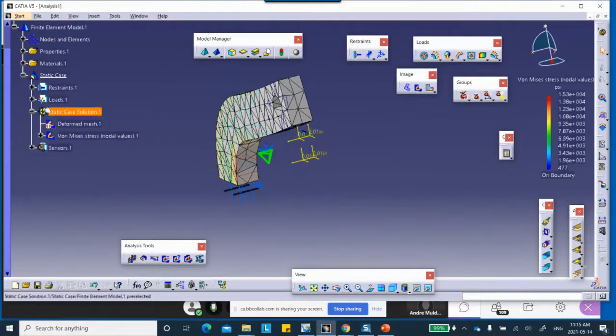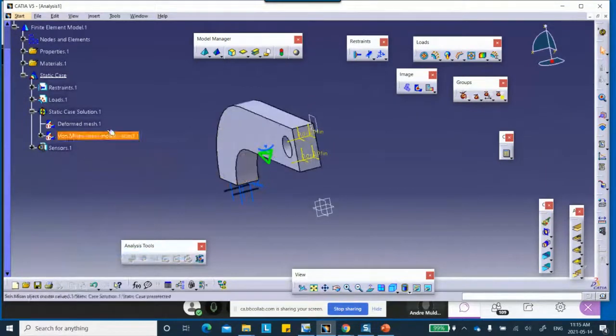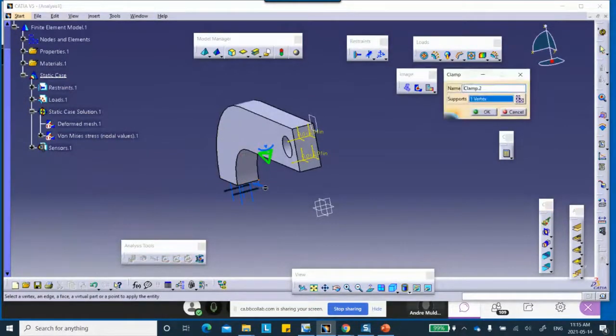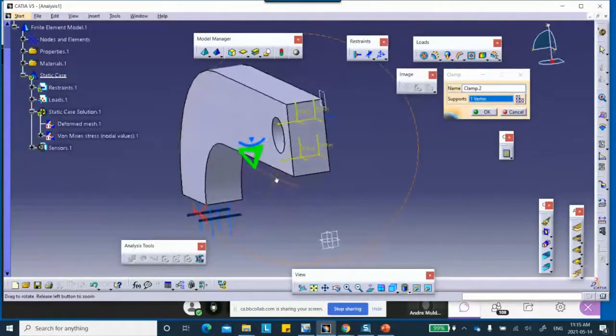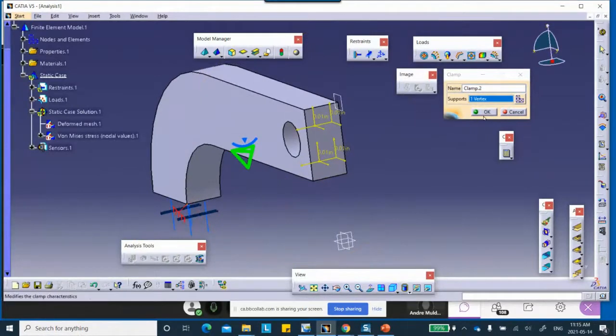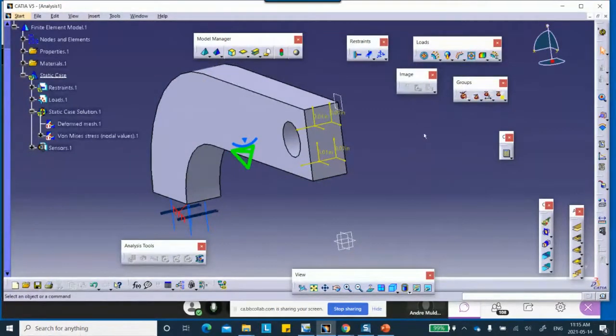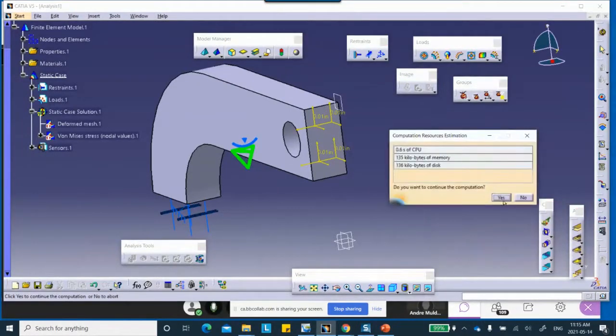Okay? But if I take this, deactivate that. If I take this clamp and instead of putting it there, I put it on this side, not two of them, I don't want this. Okay, if I put it on this side, the colors may look okay, the numbers will not be okay, and so if you use a clamp, if you're lucky, it may work, but use your engineering judgment.